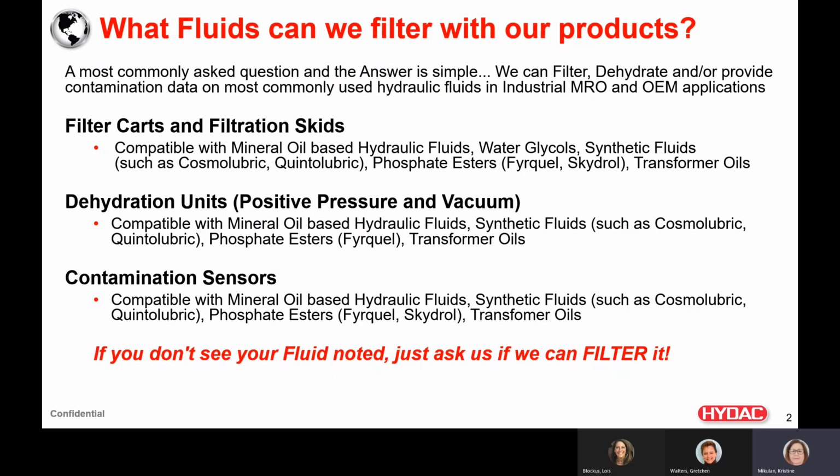Contamination sensors, we can count ISO count data on any of our mineral oil-based hydraulic fluids, our synthetic fluids, phosphate esters, including Fyrquel and Skydrol, as well as transformer oils. If you don't see your fluid noted in the list above, just ask a member of the Filter Systems team if we can filter it, and we'll be happy to let you know.